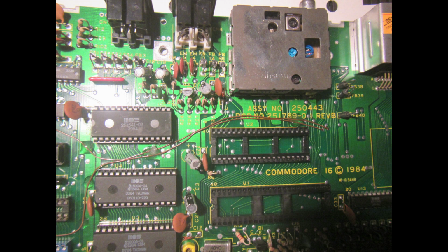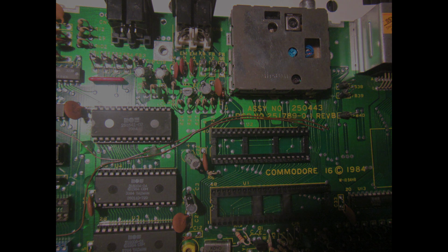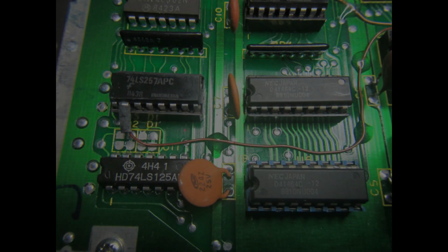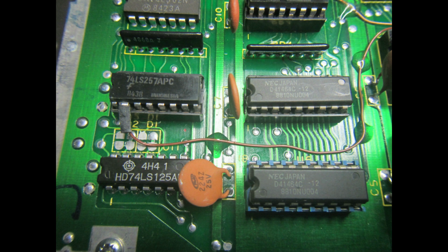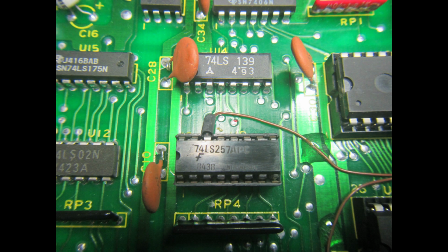Then I soldered two wires to a couple of vias that are connected to A14 and A15, and secured them to the PCB with a few drops of epoxy. After soldering the 4 sockets, the 4464 DRAM chips just go straight where the two 4416 used to live, and both U7 and U8 have instead one pin lifted out of the socket and soldered one to the A14 wire and the other to the A15 wire.